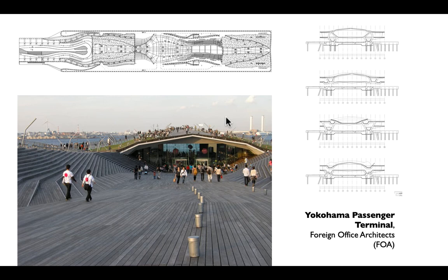So it's got this kind of, again, like a beam arch, a shallow arch that works in bending, but also mostly in compression. They're using the strength of that to put a pedestrian roof over the top of it. And then in the longitudinal direction, they're tuning all of the folds to provide ramped access up and down to the terminal itself. So using the flexibility of the folded plate principle, every bit of the structure here, again, is on a fold, right? So everything has got that kind of flange and web relationship, right? That kind of structural depth.